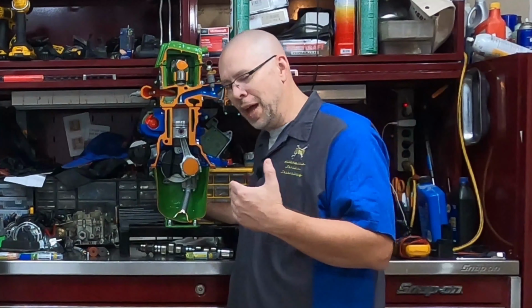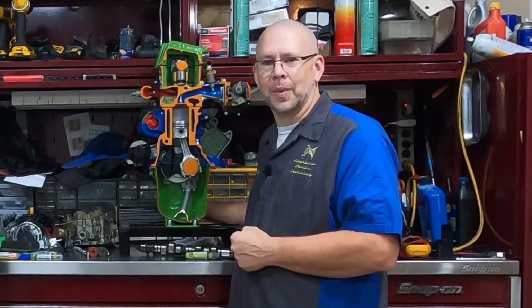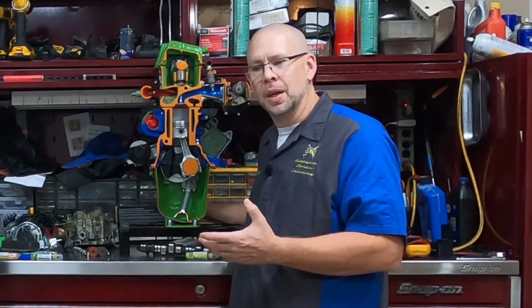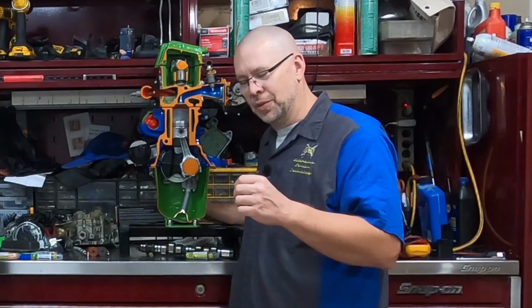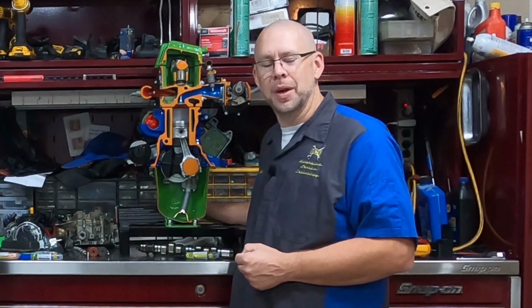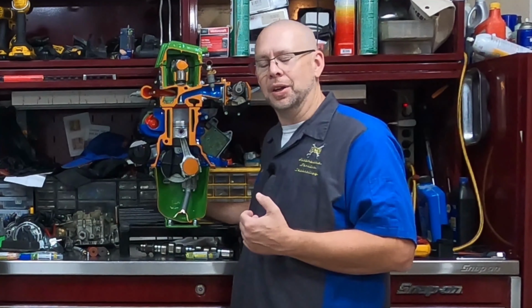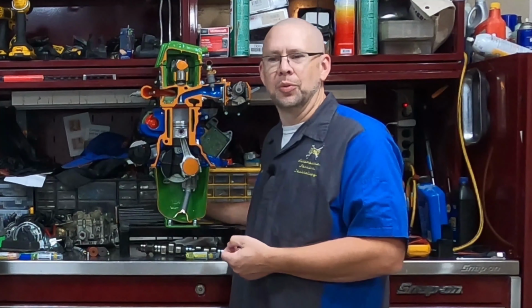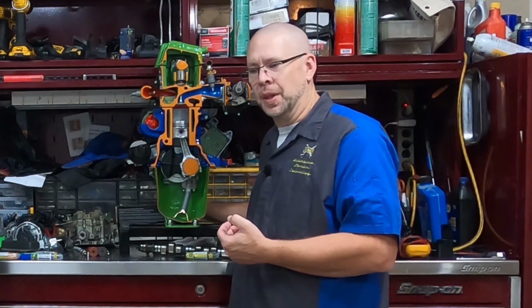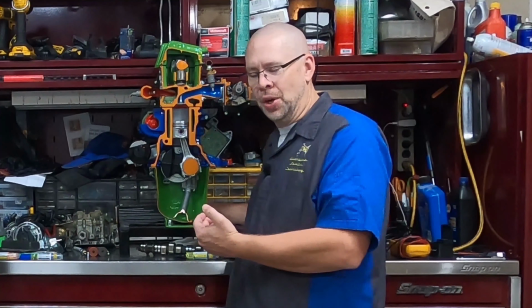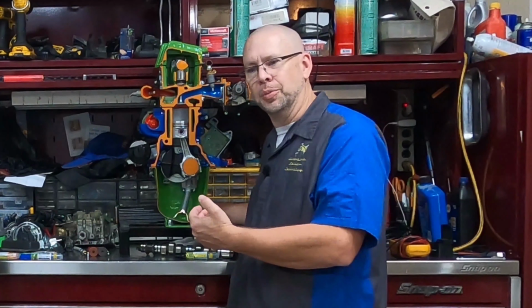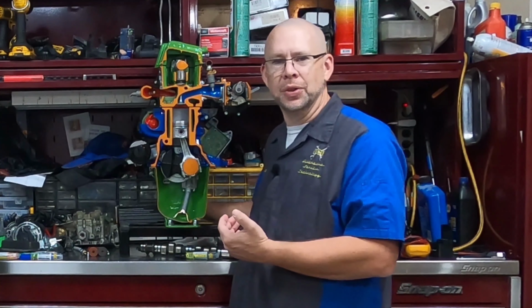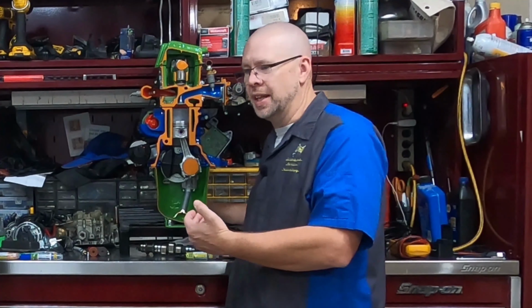Then we went to vacuum modulated timing. So now we're going to use engine vacuum, because as you find, vacuum is related directly to load. So it's great for any place we need to measure the load on an engine. So we had our vacuum diaphragm on the distributor, where a change in load through vacuum would cause a change in timing. If we had less load, we tended to run a little more advance. With more load, we ran less advance. And that was just simply done through using the engine's vacuum on a diaphragm.